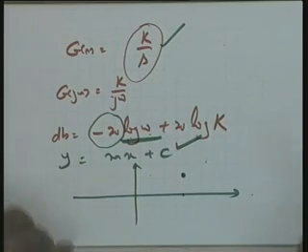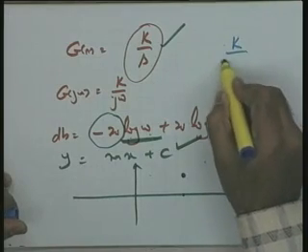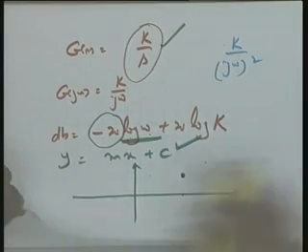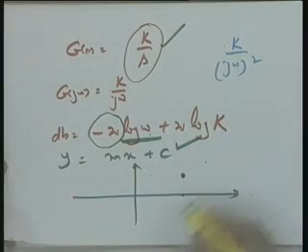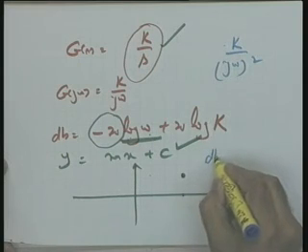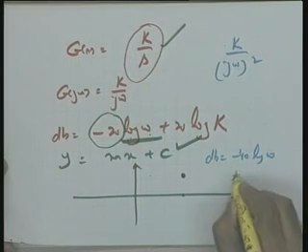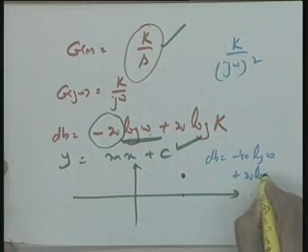Okay? Now, a question please, let me change a color here: k by j omega squared, can you help me? This is okay, that it will be minus 40 dBs per decade. I am sure you know it, but help me about the point through which it passes. You can write this equation, the basic equation you should write. The basic equation is dB equal to minus 40 log omega plus 20 log k.